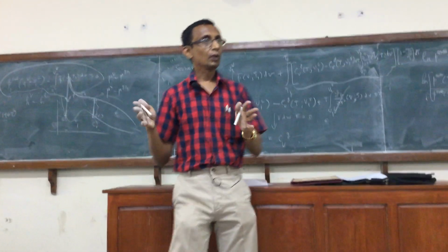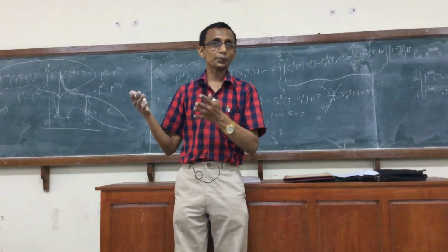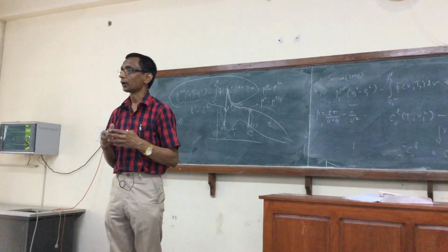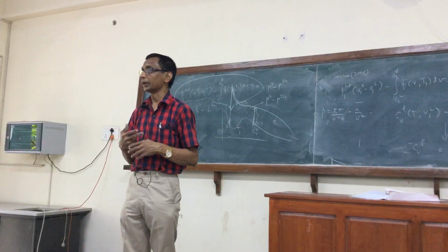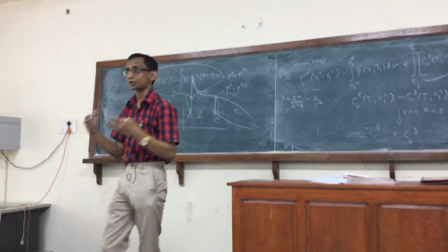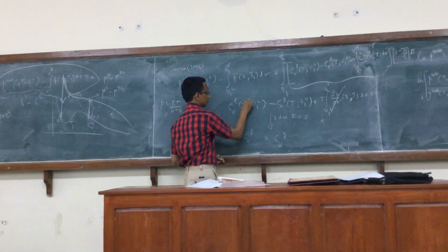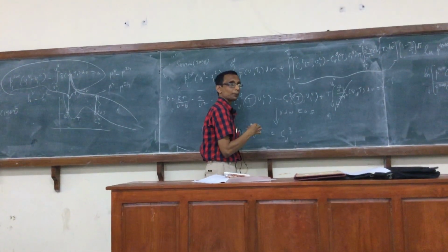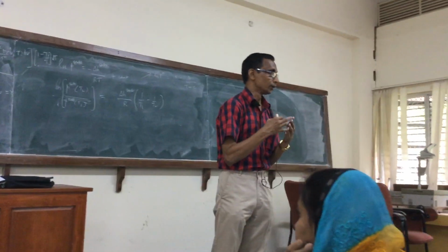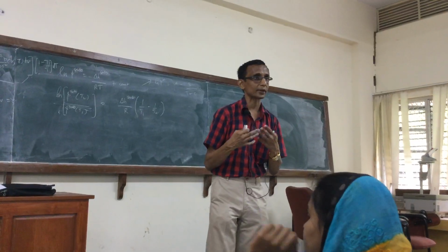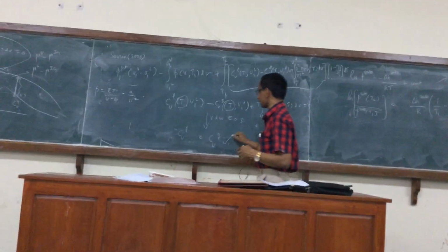Just as the vapor volume and liquid volume are different, the specific heats also will be quite different. The liquid is a completely different phase compared to the vapor. You can see how wrong one could be if you are using Maxwell's rule, unless you are close to the triple point where this condition may actually be satisfied, because the temperature is an important parameter. It will not be satisfied at all temperatures, but closer to the critical point, where the properties of the liquid and vapor become closer and closer and sort of collapse at the critical point, you expect this condition to be satisfied.